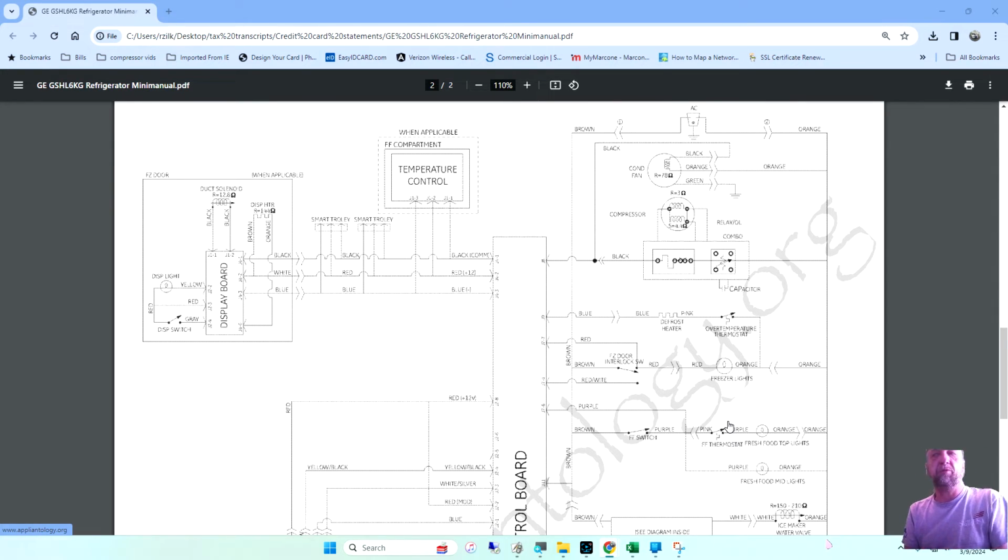But did the evaporator fan stop when that compressor stopped? No, the evaporator fan kept running. Well, it has to be an electrical connector problem. If the condenser fan and compressor shut off, remember, they both get power from the same relay on the board. So you need to determine whether the board is continuing to send power out or not.